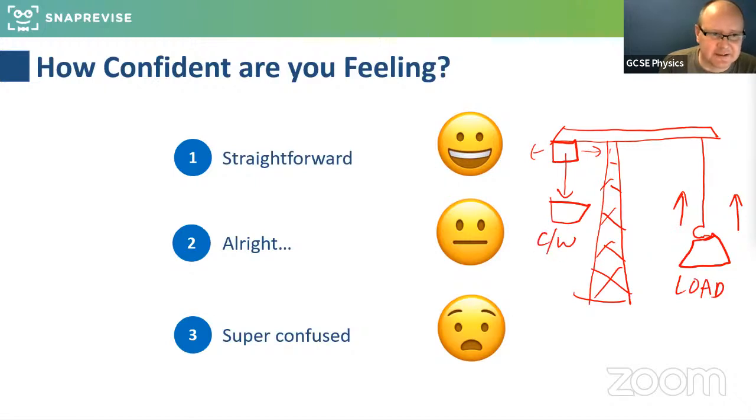And there's our counterweight. And there's only a little bit of assistance required from an electric motor, so electrical energy put in in order to assist the process. Whereas if you had no counterweight that could go down, then you're going to use all electrical energy input to lift the load. Of course, that system is only going to work if you've got something else on the load side you can then lower down again. So this isn't always applied, but my example of a funicular railway on a cliffside using water and people as movable counterweights is another good one.